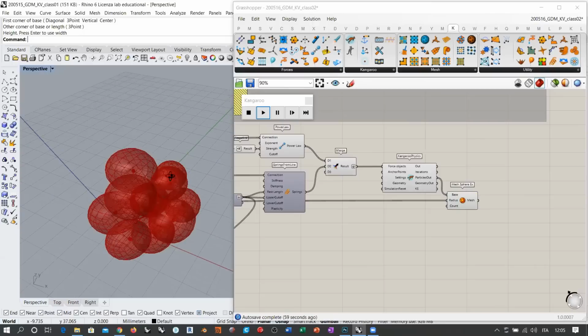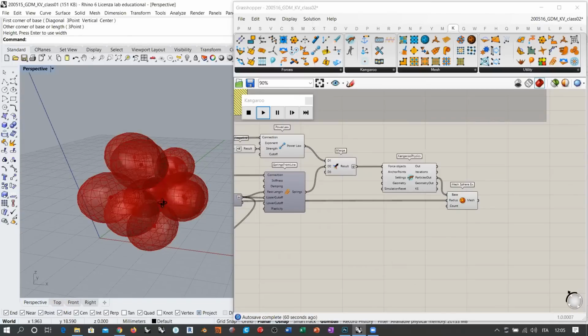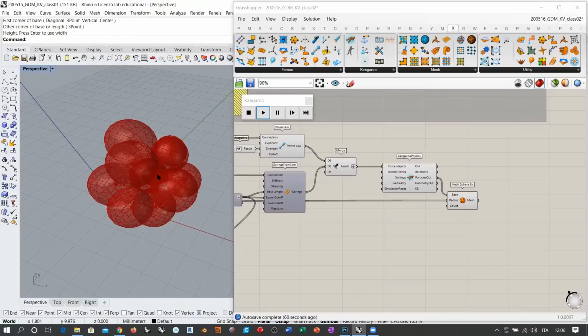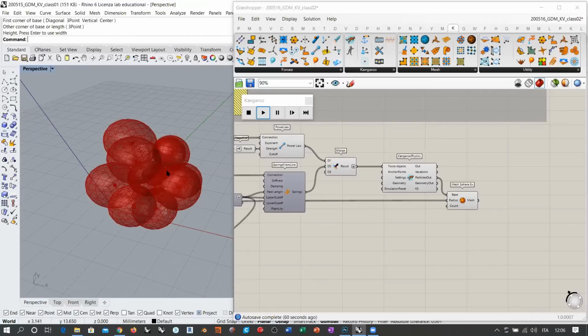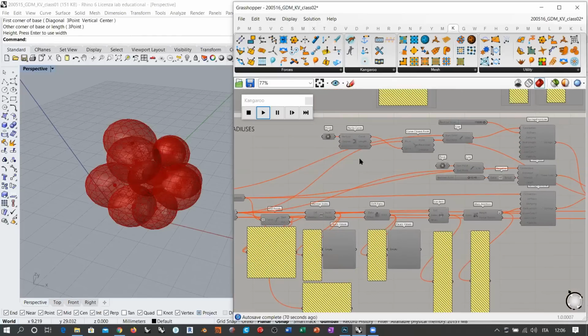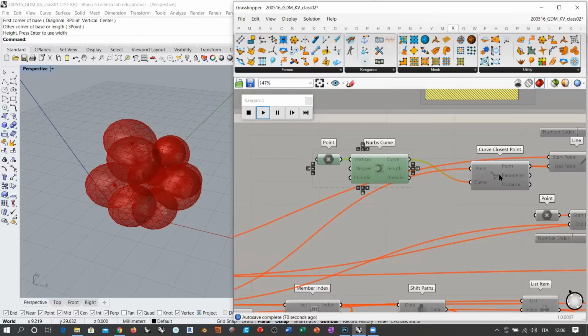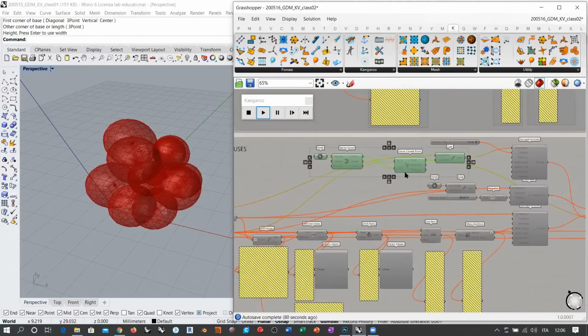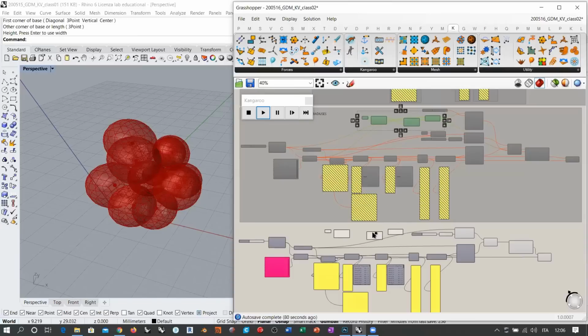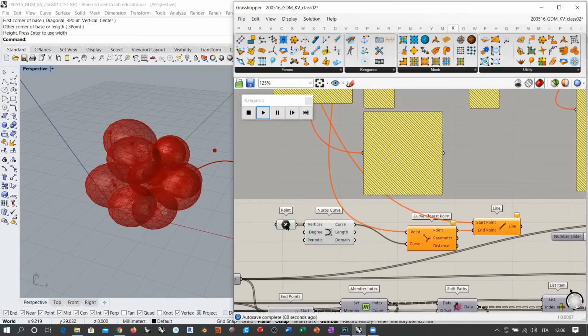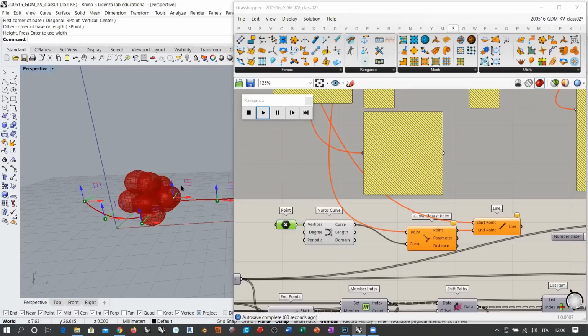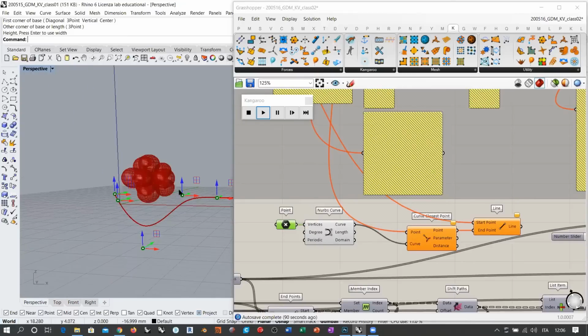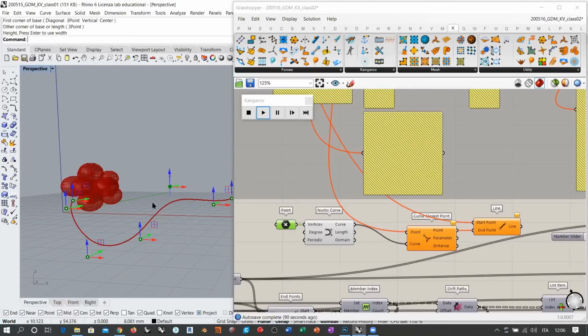And of course, even in this case, you can work with attractors. So if you want to pack these circles using an attractor curve, you can use it. It's very simple. In this case, it's going to be a 3-dimensional attractor, of course. But anyway, it's more or less the same thing. I'm just going to copy paste and create this curve closest point here. So I'm going to copy it and take these points here, and instead of having them all flat in the XY plane, I'm going to move them like this.